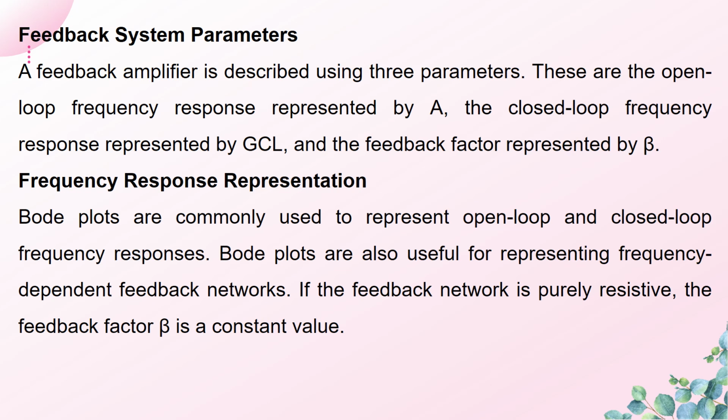So next let's see about frequency response representation. Commonly Bode plots are used to represent open loop and closed loop frequency responses. Bode plots are also useful for representing frequency dependent feedback networks. If the feedback network is purely resistive, then the feedback factor beta is a constant value.